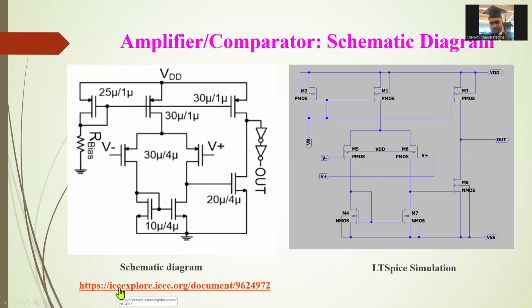Before that, here is the preference, because during this lecture, during this video, I'm not going to explain how to calculate this WL ratio. To calculate the WL ratio is very complicated compared to the logic gate. Okay, for the logic gate, we just need to select the minimum WL ratio to handle the current.